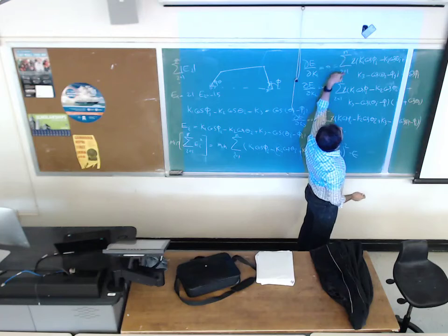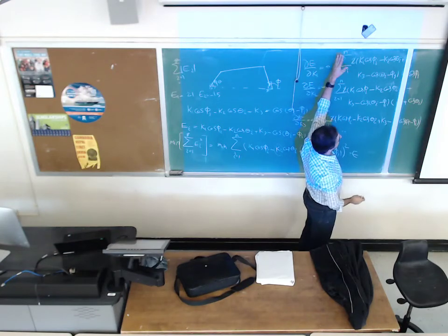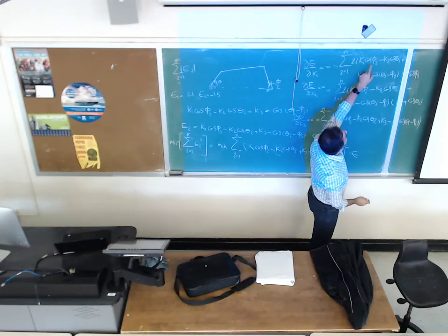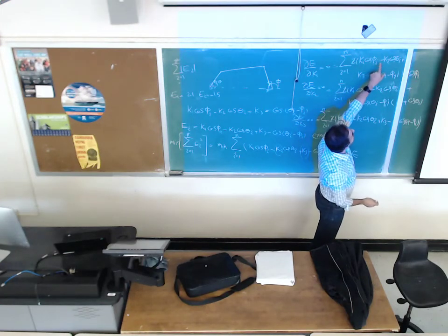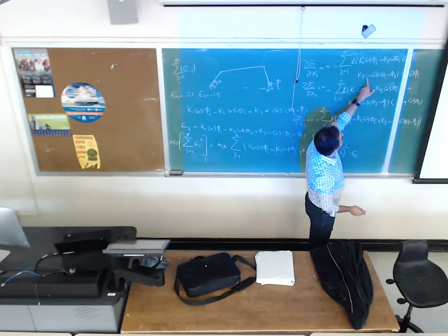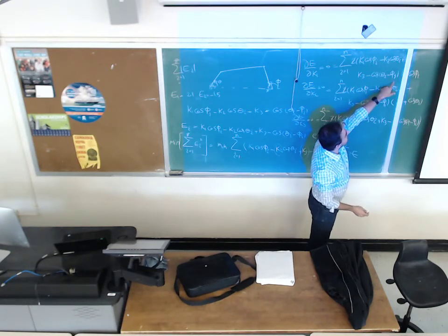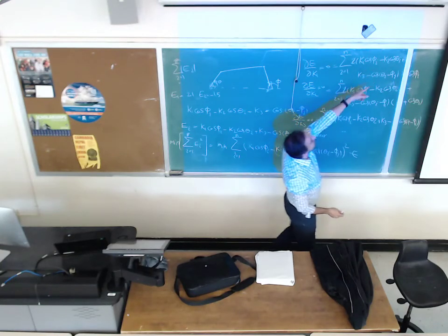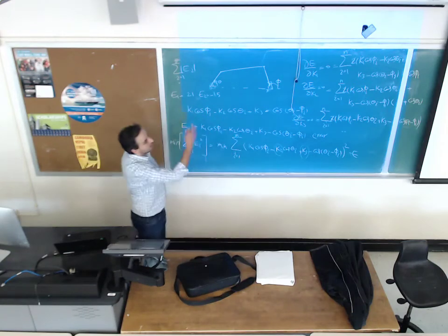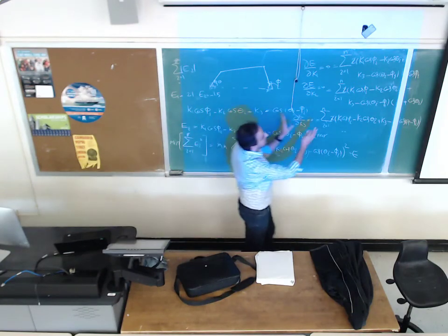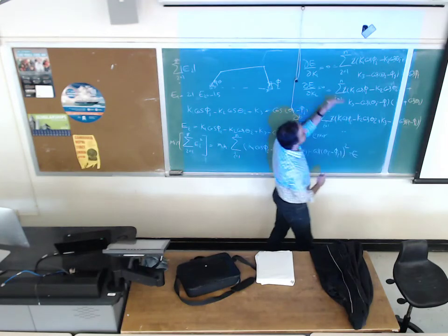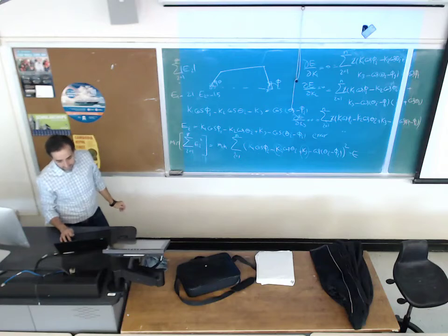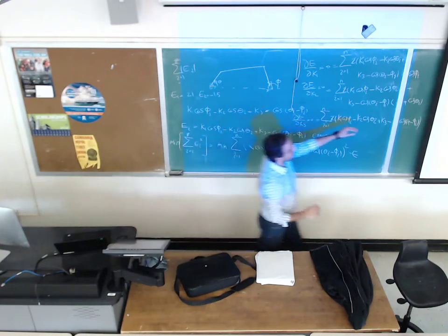whatever is the number of angles, precision points that you have here, you find this summation: K1 times cosine of phi1 minus K2 cosine of theta 1 plus K3 cosine of (theta 1 minus phi1) times cosine of phi1, plus K1 cosine of phi2 minus K2 cosine of theta 2. So we do all the math, we get three equations with three unknowns. The unknowns would be K1, K2, and K3. It's going to look like this.